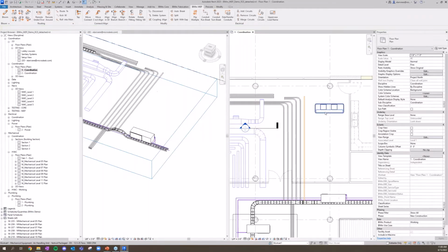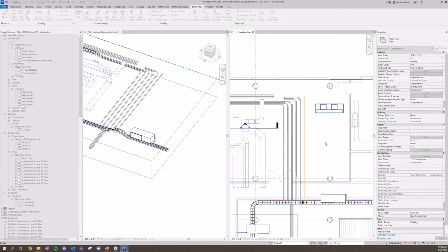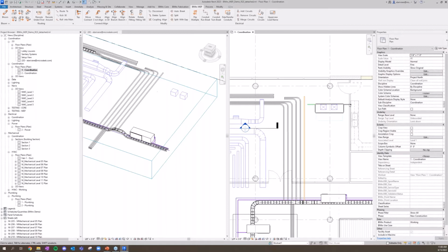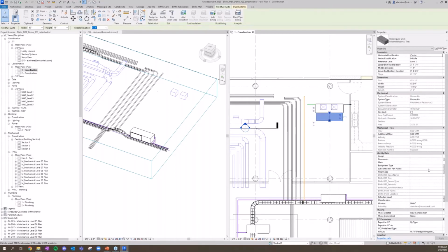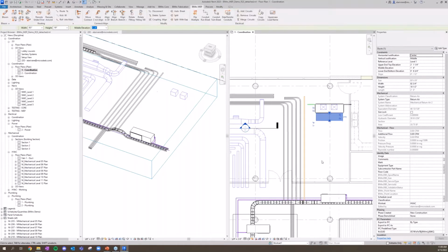Clicking OK here, coming over to that equipment. If we bloom that out, there we go. An extension coming out of each, and those extensions also getting the correct work set. We see HVAC down there, even though I'm in work set 1 down here.